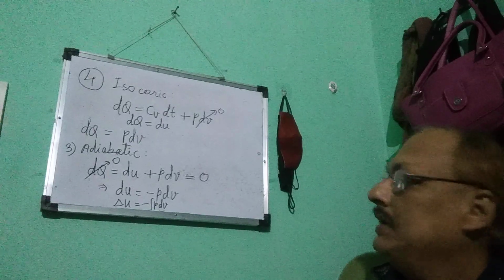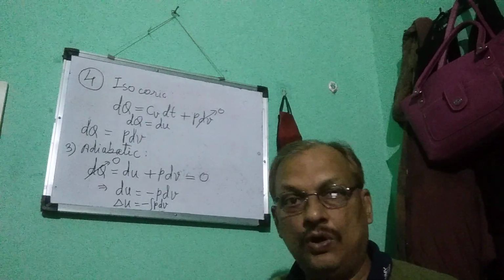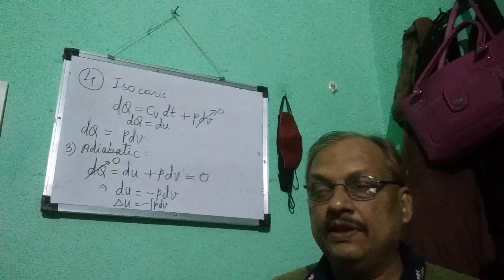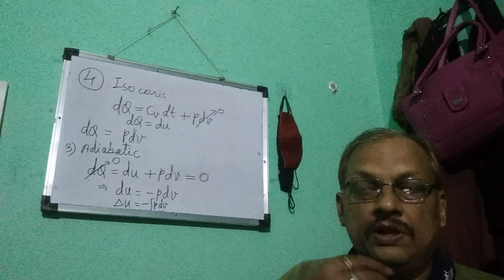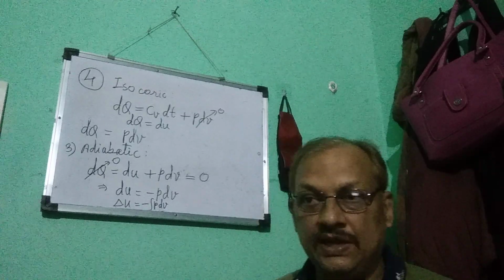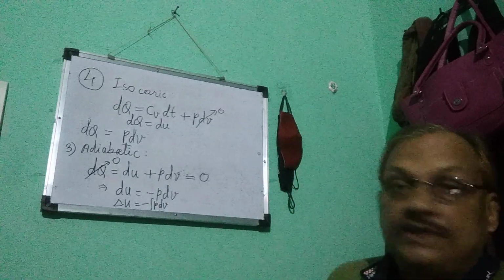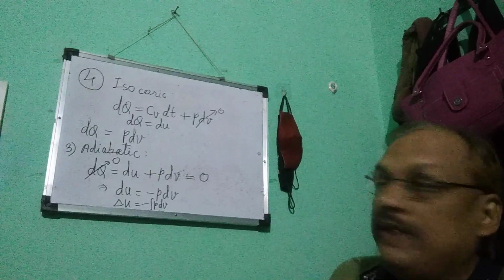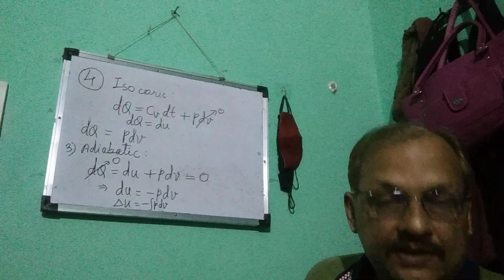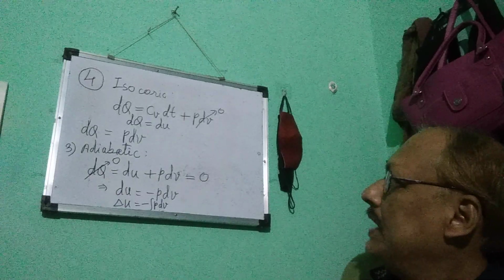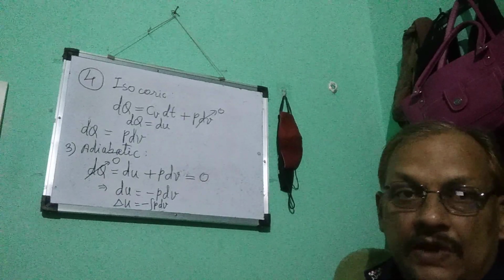If data for the internal energy gain is given, suppose the temperature is increased by this much and mass is this much, and cv of course will be given, where cv is the specific heat at constant volume, you could calculate the internal energy gain.